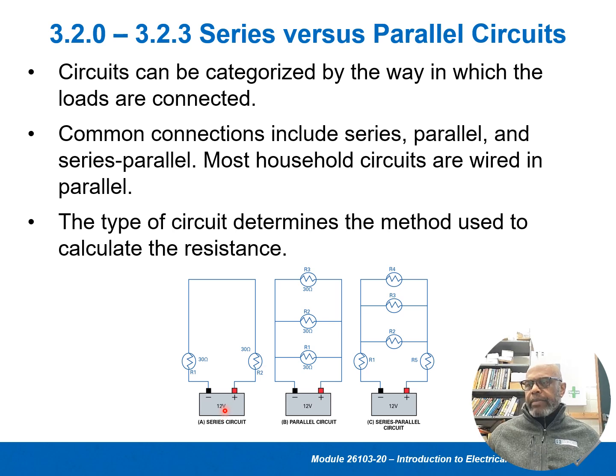The rule is that a series circuit, when it comes to voltage, is the sum of the individual loads. If you add up the voltage drops, let me put it this way: if the resistance is the same for both of these, the voltage drops for each one will be the same. So resistance will determine how much voltage that load will drop. Okay, so it's important we can look at some other things as we go in the classroom.